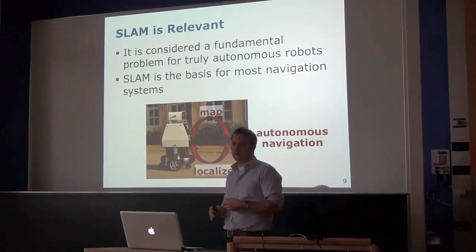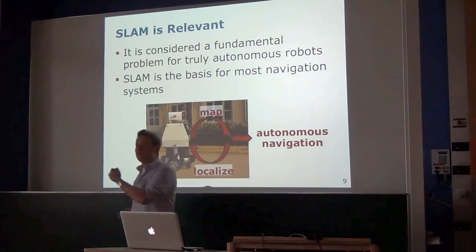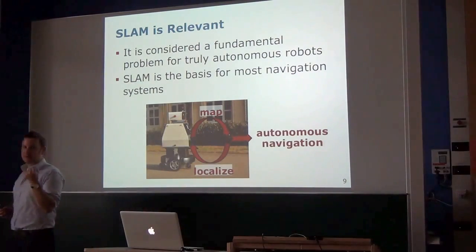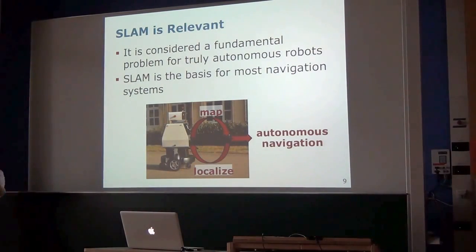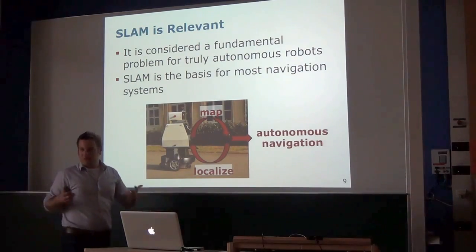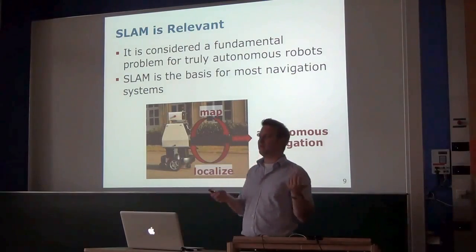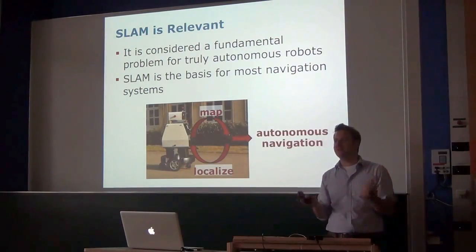So we don't use landmarks. There are different ways to address the problem. If you know what you're going to observe in your environment, landmarks are great. You have a good landmark detector, because it can dramatically simplify your problem. If you don't know what to expect, it's really hard, because if your landmark detector doesn't work, well, there are no landmarks that you can observe, you don't have any observation.